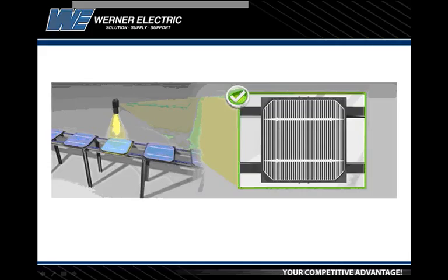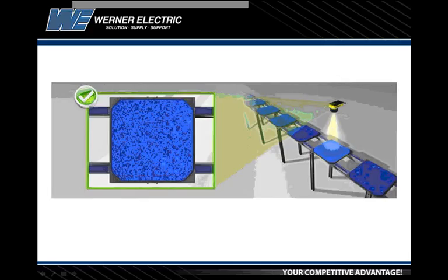All right, here's another view of the solar cell after the electrical traces have been applied to it. If you look there at the defective unit, one of the traces is broken, so that will affect the electrical function of this solar cell, so that one needs to be kicked out and either reworked or rejected.